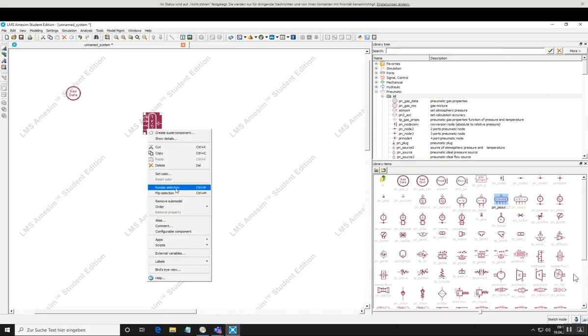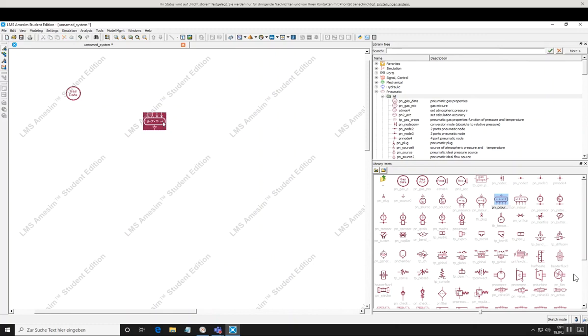and let's have a short look at the quantities, at the properties. We have temperature as a boundary condition, temperature of the air. We have pressure of the air that goes into this object, and enthalpy and mass flow go outside of the object. So this will be a result of your simulation. You don't have to know it. And I need two boundary conditions.